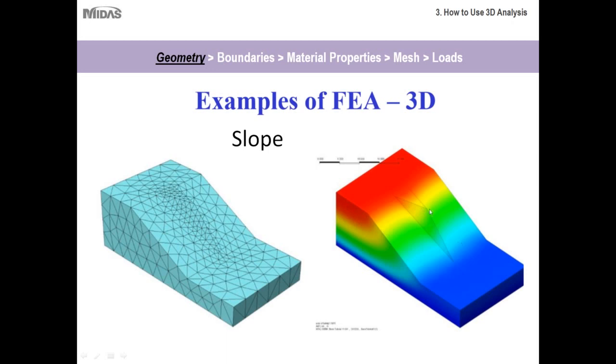So it really depends on your project geometry and your project type, you'd decide which elements to use. But the main thing to take away from this is that each has its own purpose and each has its own shortcomings and weaknesses. The main strength of 3D solids, obviously, is that there's no limitation to what you can model, but the drawback is that the analysis takes longer. There are more variables to take into account. Whereas with 1D elements, the analysis is very simple and very fast, but it's more limited in terms of the geometry that you can model.